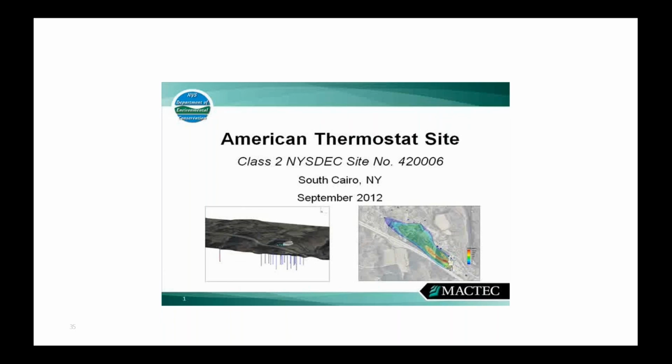Again, this is another 3D model that I'll run through. We went in and we did passive diffusion bags, put those in these really long wells to see if we could find out if there were contaminant gradients. We did geophysics to find out where those fractures were, put it into this 3D model to model where those most transmissive zones were, matched it up with the PDB samples and Packer samples that we collected, and came to a better understanding of what was actually going on here.